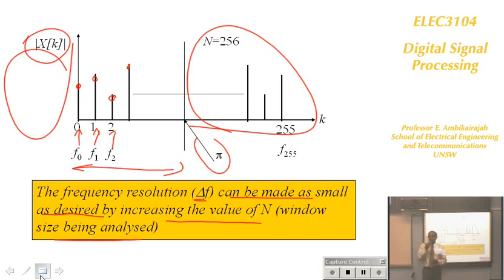But a non-stationary signal like speech changes every 20 milliseconds. So you can't have a large window. You have to analyze every 20 milliseconds. Otherwise, the frequency spectrum that you get is completely an average spectrum, which is not correct. Because the spectrum of the vocal tract, the resonance, changes every 20 milliseconds. So the window size cannot be made very big in real signals, right?